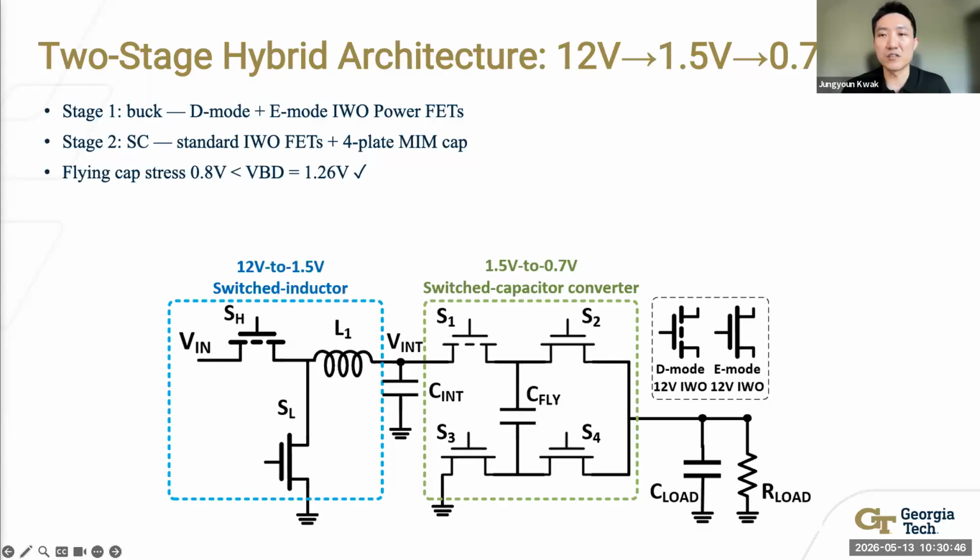The switching node connects to the cobalt, zirconium, titanium thin film inductor, which filters the pulse width modulation voltage to the DC average. An output capacitor removes the remaining ripple. The duty cycle is 12.5%, set to give the 1.5 volts output from the 12 volts input.